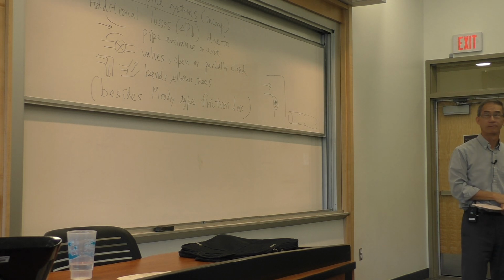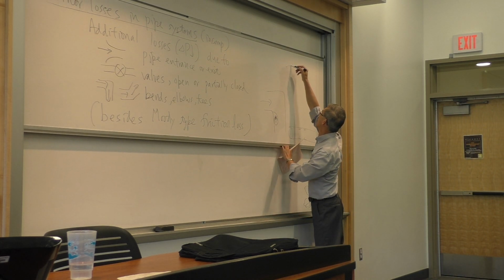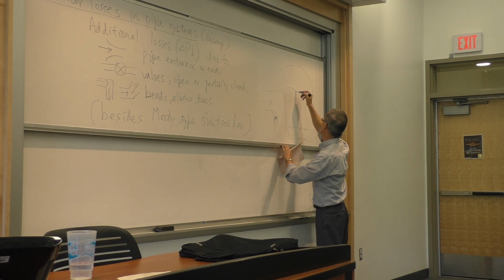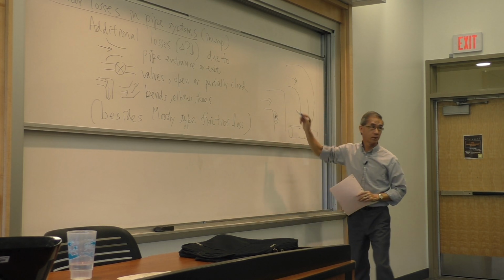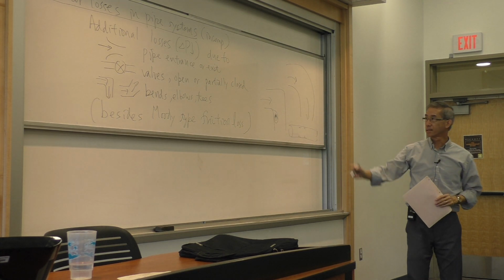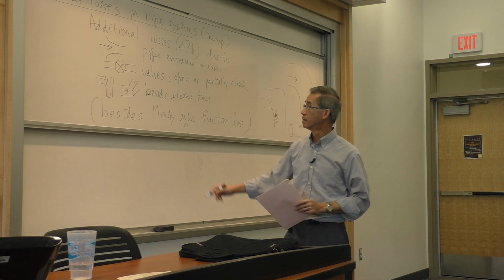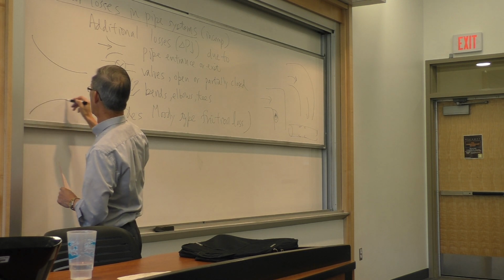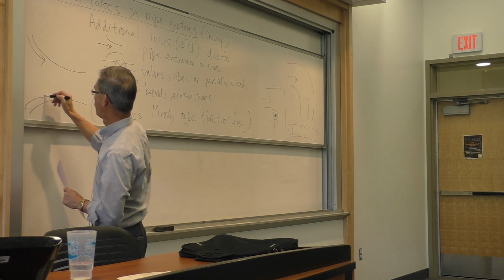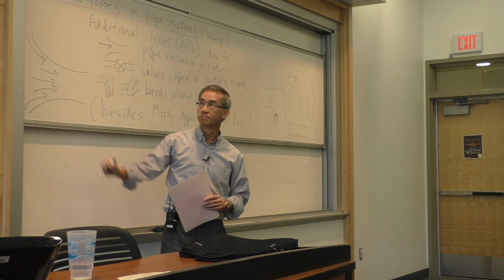There are different elbows. This is maybe the worst elbow. There are others that have a huge radius, relatively smooth, and you have less losses than this one. It's just like the intake. The diagram there shows a sharp intake. I can have a bell mouth intake like this one, very smooth, so the flow can follow with minimum separation on the edges.